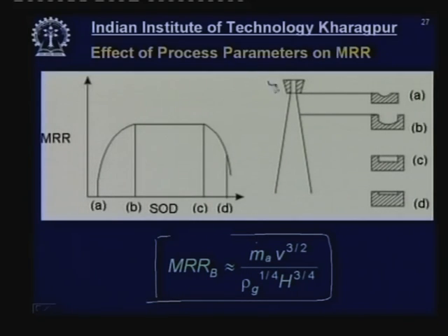This small piece is my nozzle, and it is issuing the jet. As the jet is being issued, it is interacting with the air molecules around it. It is a submerged jet, an air jet within the air. So, it will entrap air from the atmosphere, and as it entraps air, there would be flaring of the jet. The jet would be very straight as it is being issued, but after a length of typically around 10 internal diameters of the nozzle, it will start flaring out.